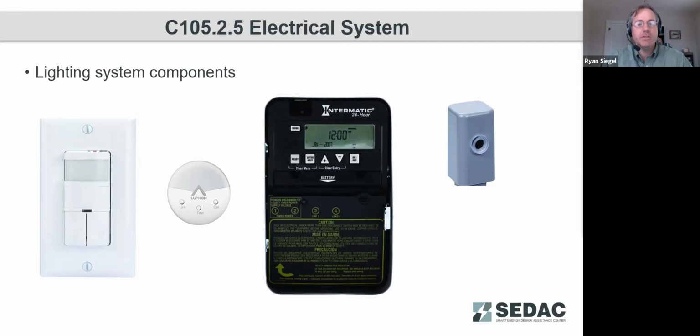So this is your occupancy sensors, your vacancy sensors, your daylight responsive controls, your timer functions for those spaces that are not covered by occupant sensing devices, photocells for exterior, your programming components, because a lot of these daylight responsive controls and even more occupant sensing controls have separate programming devices, which you may have caught on a couple of slides earlier.